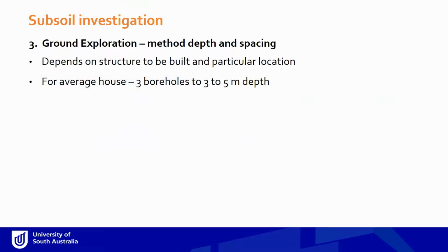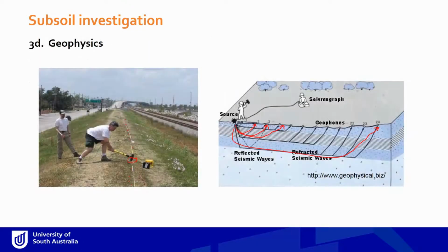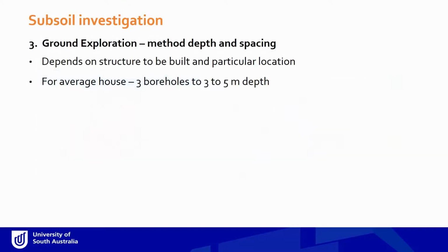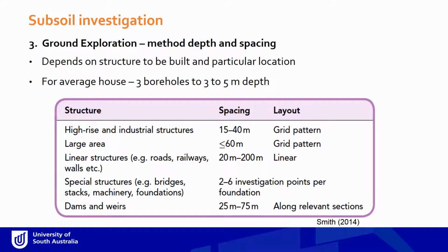Now, so far we have talked about ground exploration and different methods of it. In this slide, we're going to talk about the spacing, or how many boreholes we need, or how many test pits we need to dig, and what sort of spacing they need to be. Now, the spacing and depth and all these sorts of things obviously depend on the purpose of the project, or what we are actually going to construct in there.